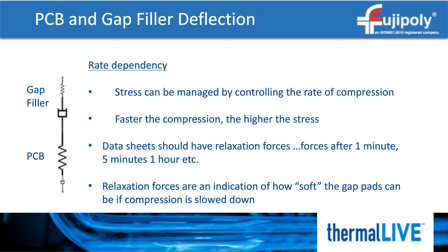The datasheet should have relaxation data. You may see this as a curve over time at a given percent compression. This can also be forces after 1 minute, 5 minutes, 24 hours, etc. The relaxation force is an indication of how soft the pad can be.